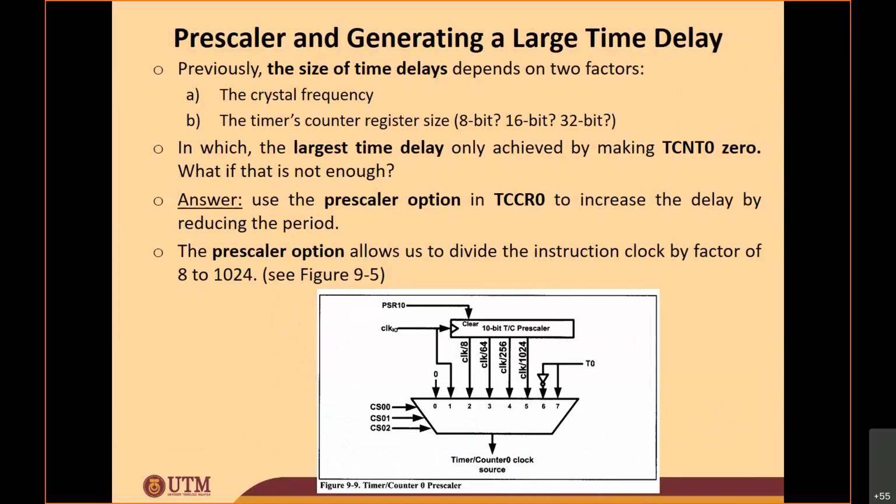Chua Xinglang asks, if we don't stop the timer, it won't affect our main program also, right? Okay, if you do not stop the timer, yes, it will not affect your main program. But as long as you clear your flag, then you can use the timer again later. But to be safe, we just stop the timer in step number 4.